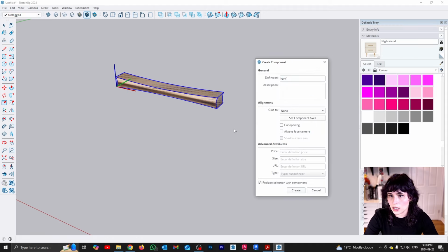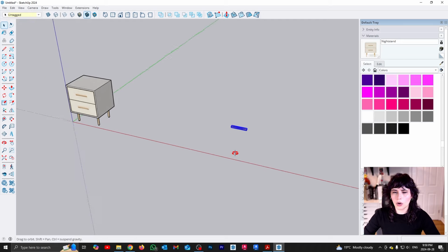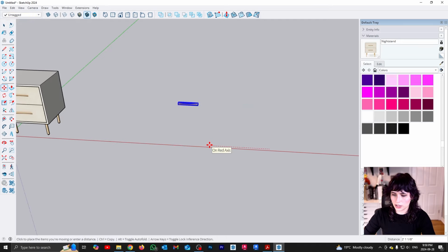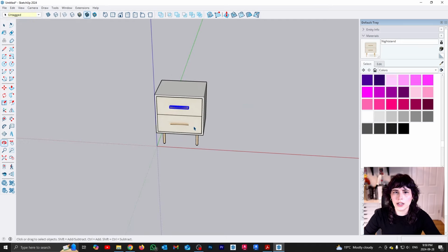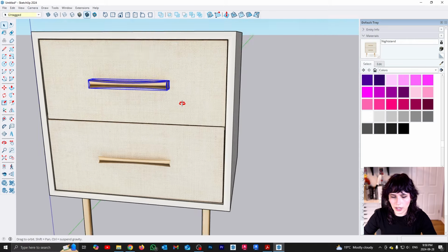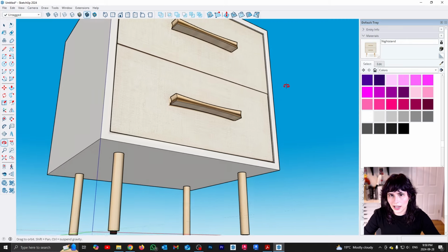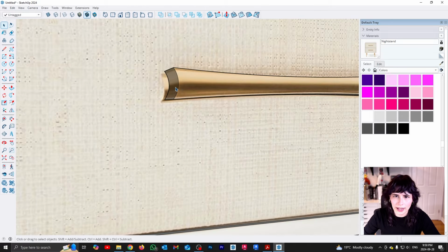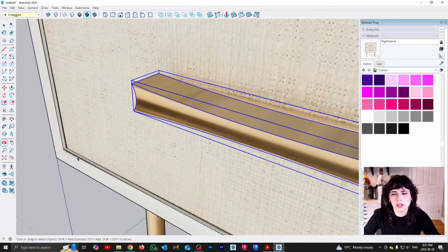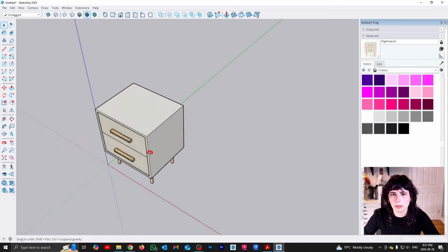This is going to be handle. There you go. And now all I need to do is move it. What was it? 8 feet, 4 plus 4, 8. And now for my second handle, all I need to do is M plus control, and we're going to copy it down. And look at that. Ooh, I don't like that. Should I model the second? No, Irene, stop yourself. Know your limit, play within it.